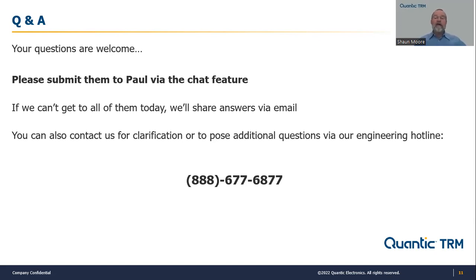Well, I think that just traces on the previous comment, Paul. What we will do is work with you to find out exactly what is important to you, and from there pick the topology that is best suited for that application. There are, for example, certain frequency bands where you can build this virtually any way that you want, especially if you're working at, for example, L band. You can build that as a Wilkinson power divider. You can have a broader frequency tapered line. You can build that as a lumped element, or you can build it as a resistive power divider.